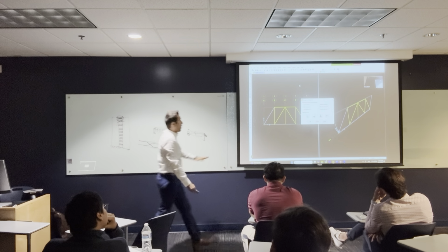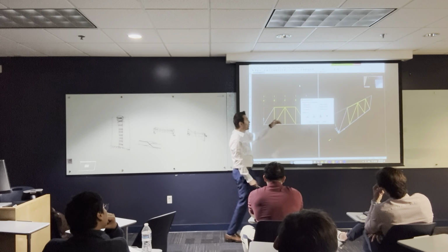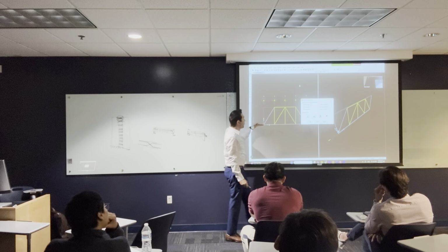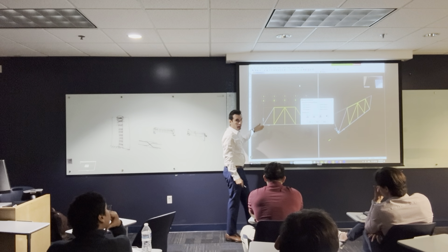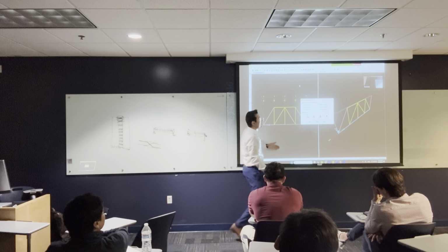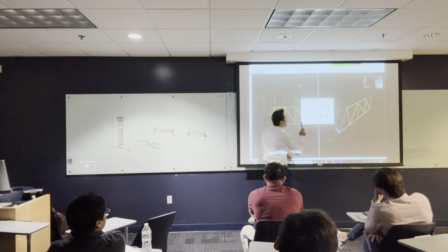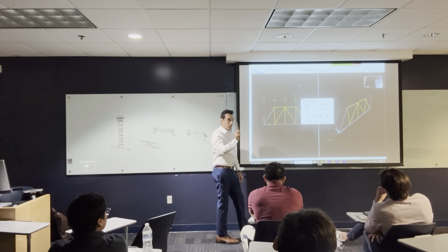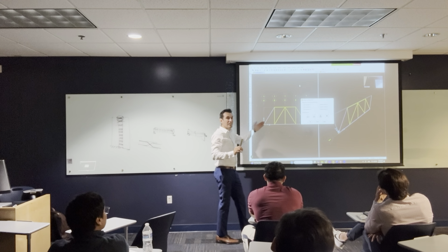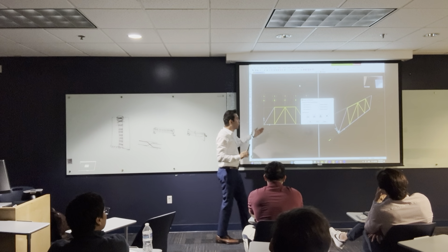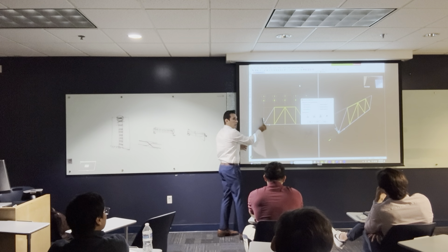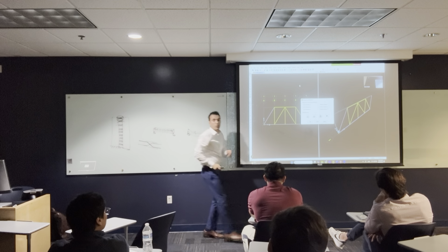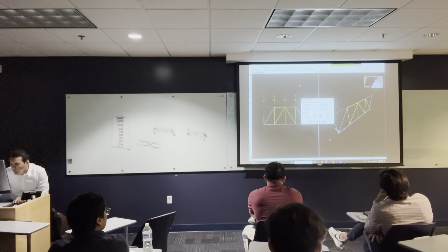So basically, translation 1 is the X, translation 2 is the Y, translation 3 is the Z. If you want this point to move only in the X direction, the only restraint that you have when you have a roller is the vertical. But since this is 2D, we only need just the vertical restrained, and the roller is allowed to move in the X direction. So basically you can pick the restraint or you can pick the translation.